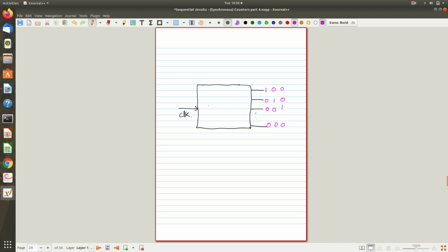So what I am using is an n-bit shift register. Instead of that counter and decoder combination, I am trying to use just an n-bit shift register. And a shift register is basically created using D flip-flops. Okay, so can I draw it in a vertical way? N D flip-flops are there. And you know how these D flip-flops are configured.